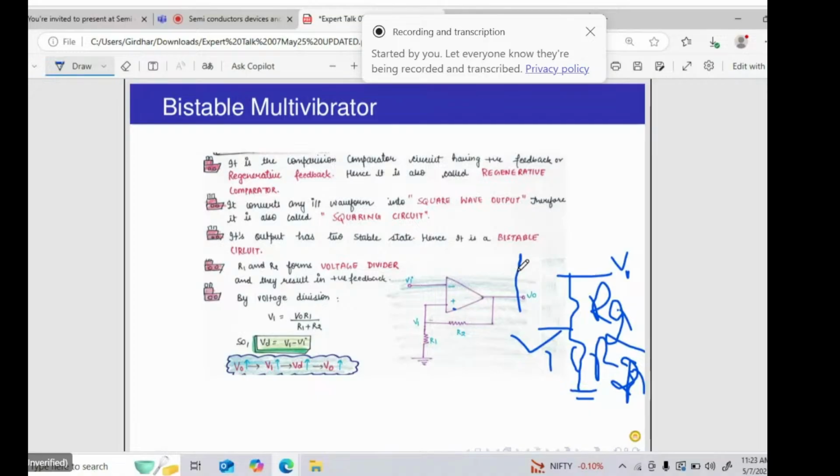If this difference input signal VD is increased, since it is an amplifier having high gain, the output voltage is also increased. So when you are increasing the output signal, ultimately you are getting a further increase in the output signal. So it is positive feedback. This is the way to test positive feedback. Increase in the output causes a further increase in the output.